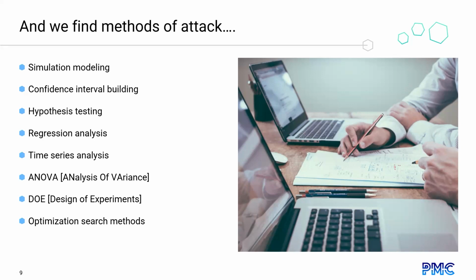So you model a system before you build it and run the simulation, look at your KPI like throughput, build a confidence interval for it. Does the confidence interval indicate that your performance, like jobs per hour, will be met? If not, thank goodness you found out now before you built the system.